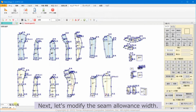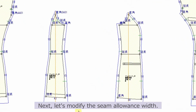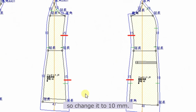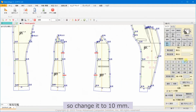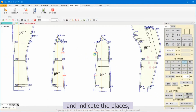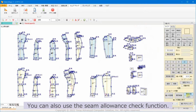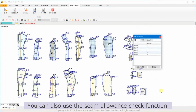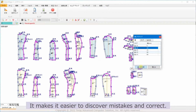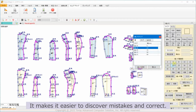Next, let's modify the seam allowance width. The seam allowance on the sides is 15 mm, so change it to 10 mm. Select the width from the panel and indicate the places, then the width is changed. You can also use the seam allowance check function. For example, it can highlight only 10 mm wide seam allowance. It makes it easier to discover mistakes and correct.